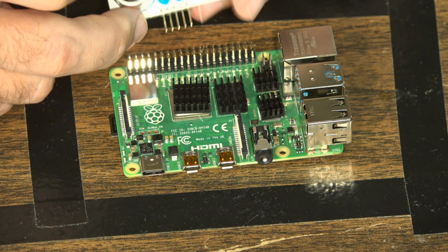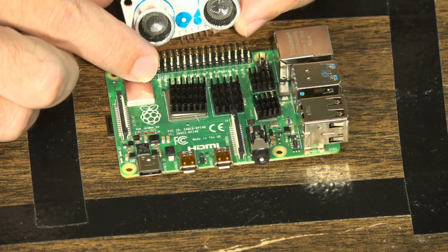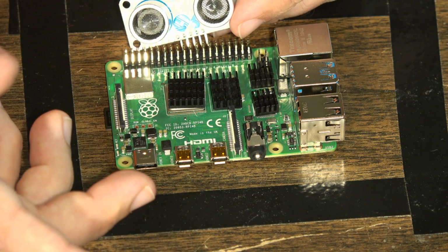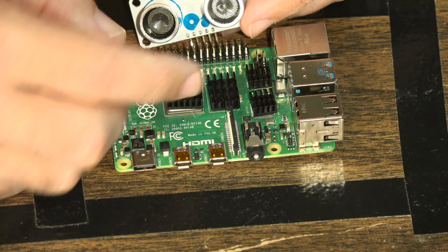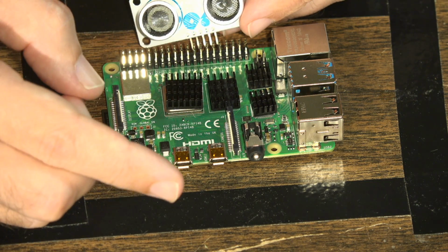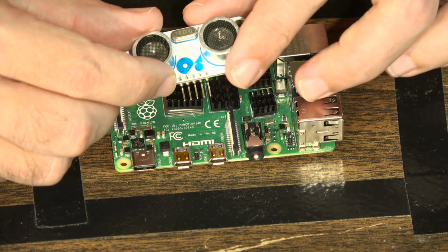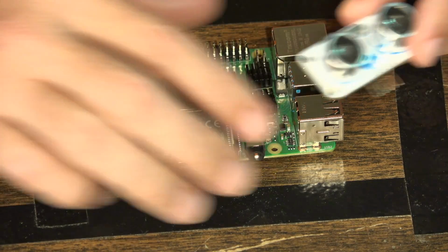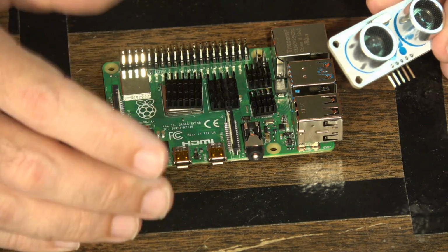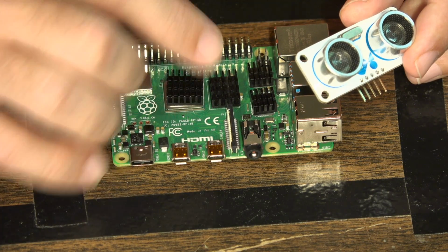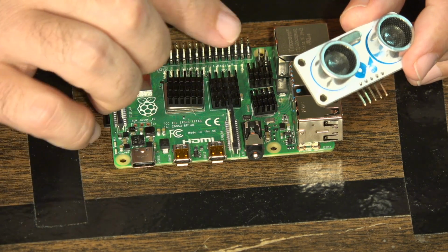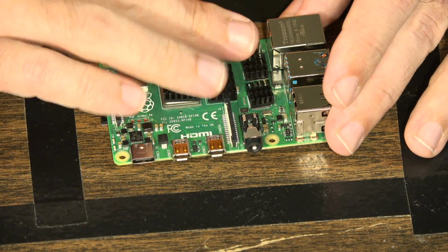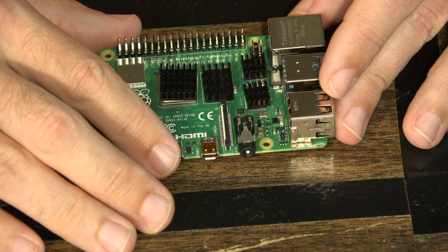So basically with this, I can have sensors connected to the GPIO pins, and then I can also have the GPIO pins connected to physical events to have happen. So I could have the GPIO pins connected to servo motors. I could have the GPIO pins connected to relays. So if, let's say, I had a water sensor, what I could have is if the water sensor detected water, then the Raspberry Pi could process what's going on, and then that could trigger that a water pump turn on, that type of thing. So these are the GPIO pins up here, and this is what makes Raspberry Pi really cool and really interesting versus just simply being a small computer.